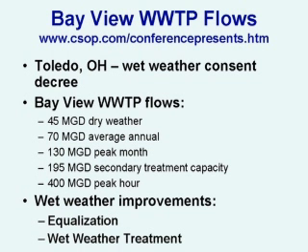So you can look at that chart and see that per acre cost, sewer separation is the most expensive, which typically is about $78,000 per acre. The tunnel system is about $21,000 per acre. Or you might look at it in terms of $1.53 per gallon of storage capacity. The treatment system is typically the least costly at about $7,000 per acre, and it is 90 cents per gallon